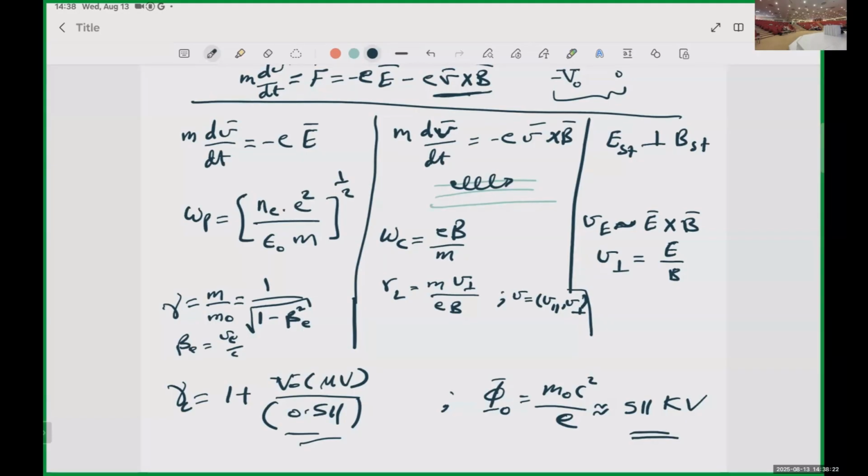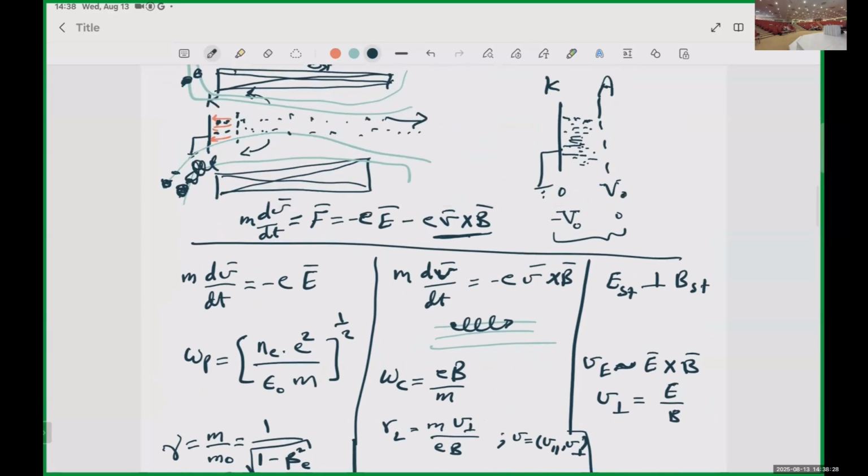So for the Child-Langmuir law, it's basically two parallel plates. Everything we do here, we assume the environment is vacuum, right? If we have non-vacuum or poor vacuum, your electrons are not going to be streaming. They will collide with air molecules, and you can't extract energy. Parallel plate is the simplest case, but you can have one plate like this and the second one curved. Imagine it is completely curved. What's the geometry now? Coaxial, right? Yes, coaxial.